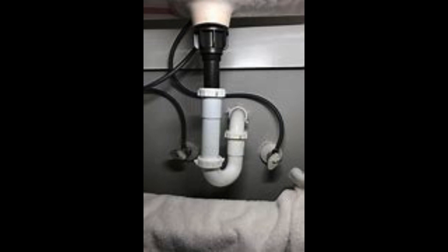5. Deficiencies in: 1. Gas shutoff valves. 2. Access to a gas shutoff valve that prohibits full operation. 3. Gas appliance connector materials. And 4. The condition and type of gas distribution lines and fittings. 6. Lack of visible bonding on gas distribution system, including corrugated stainless steel tubing (CSST).